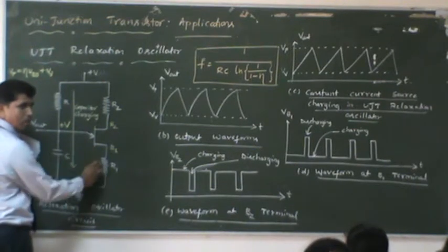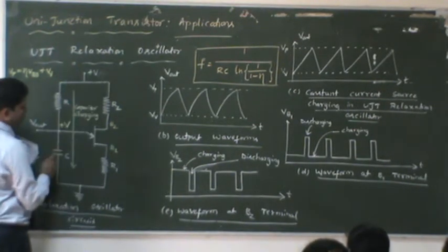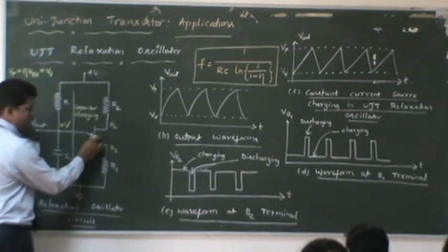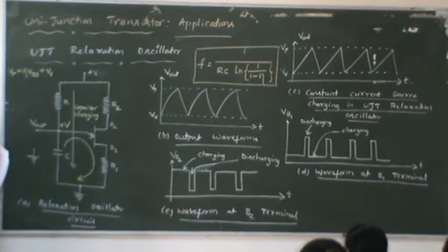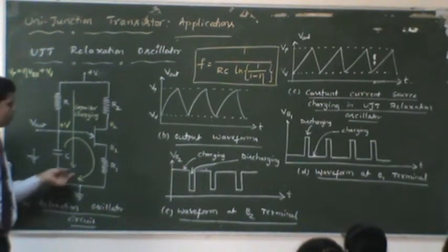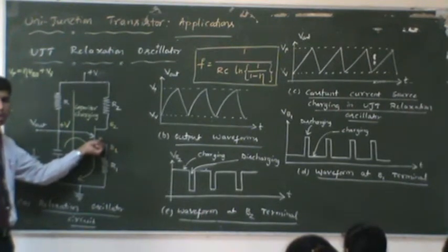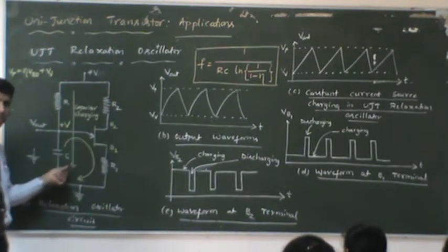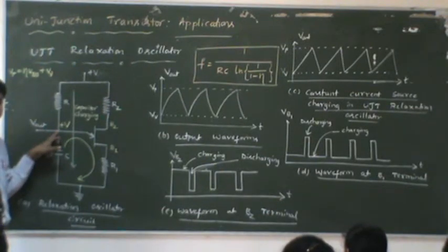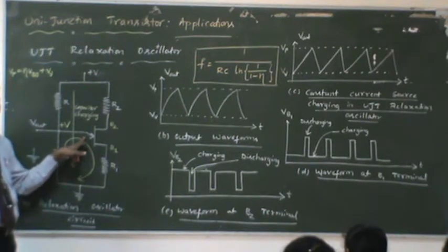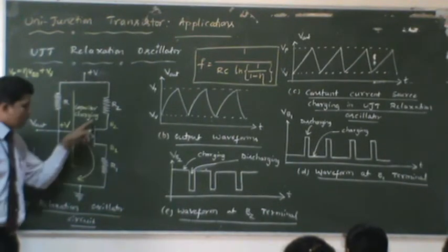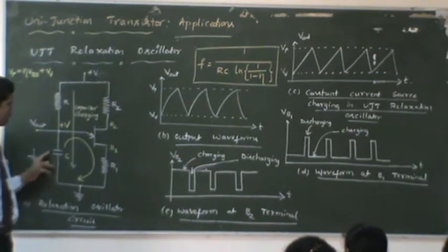Now the capacitor will start discharging. Earlier it acquired the charge through the supply voltage. Now it will start discharging because this has been turned on. When this has been turned on, the capacitor will start discharging through like this to the ground. It loses charge. How long can it lose charge? Again look at the diode here. As long as the diode is on, the capacitor keeps losing charge, meaning the voltage at this point keeps dropping. The situation will come where the diode again gets reverse biased. Now this will act like an open circuit. Again the capacitor will charge to plus V.